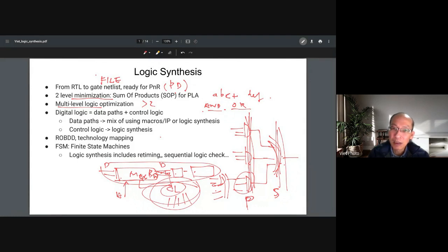Say you make a very fast multiplexer, where the usual delay is 100 picoseconds but yours is only 50 picoseconds. You box it and provide the information about timing, power, area, and pins that people need to use it. That becomes IP.